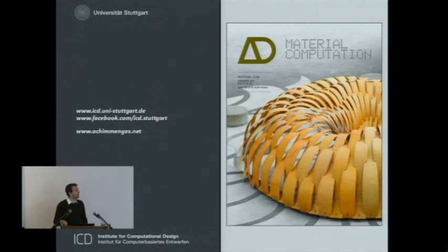Yeah, there's actually a nice photo. What really happens is that the very thin plywood strip meets the ground about 20 centimeters above the ground, and it's held from the back just with a simple notch. And you need to keep it elevated 10 to 20 centimeters, because if not, it gets affected by moisture. Then obviously the creep of the wood is accelerated, and it would be quite a problem for the structure. So the actual system ends, and you can see that here. That's why you have this shadow gap of 10 centimeters.